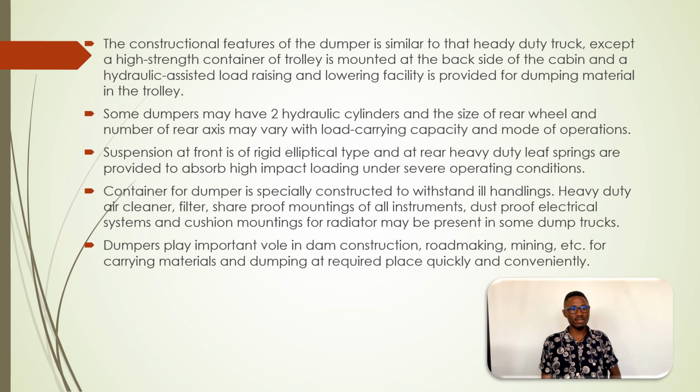We go ahead and say the construction features of the dumper are similar to those of heavy duty trucks, except a high strength container or trolley is mounted at the back side of the cabin, and a hydraulic assisted load raising and lowering facility is provided for dumping material from the trolley.